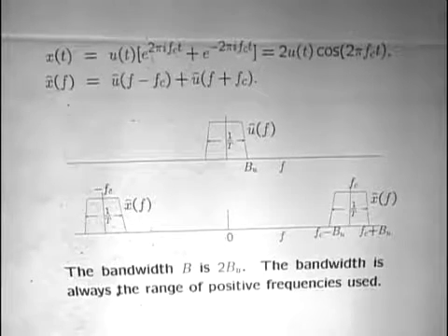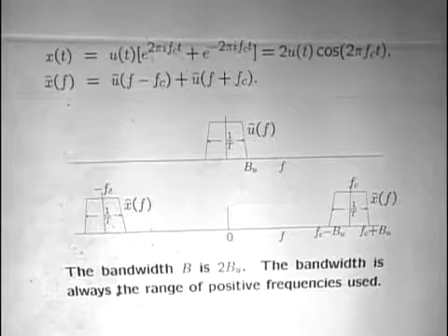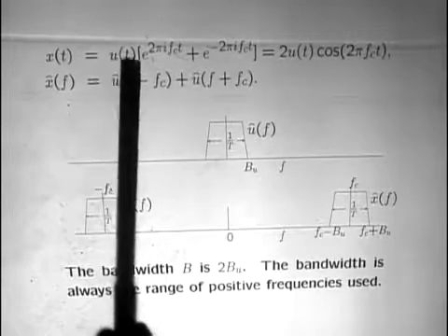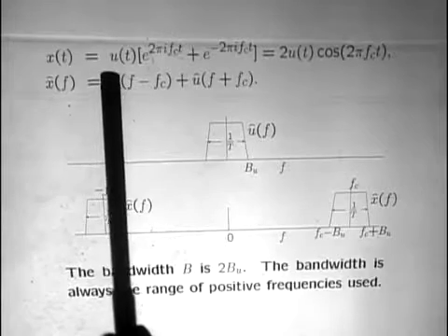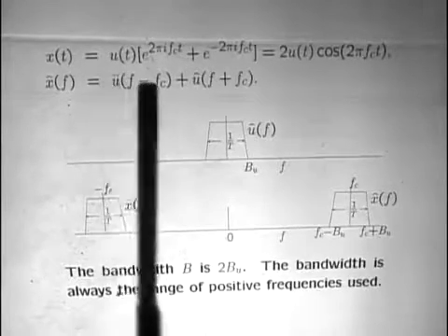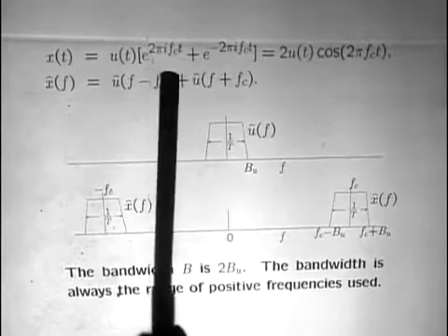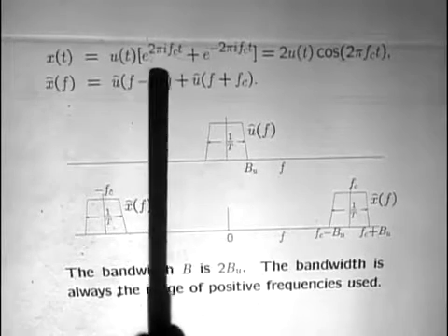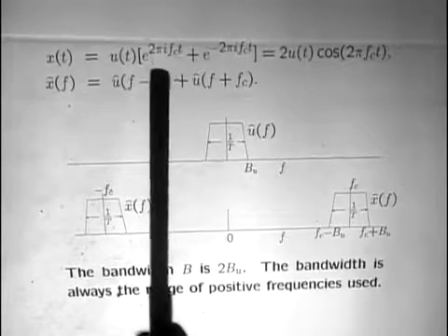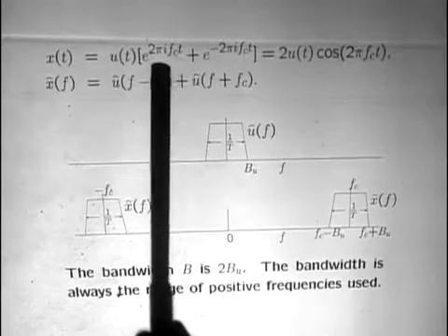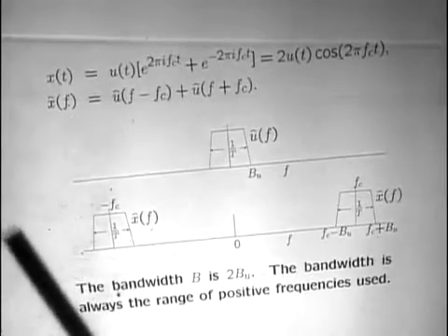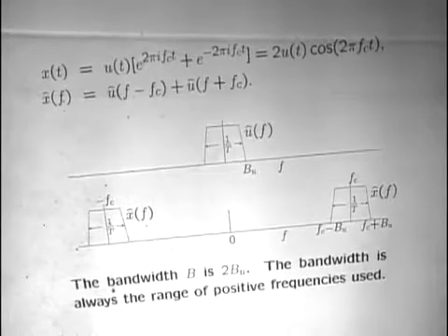And in frequency, what this looks like, since all we're doing here is, by this shift formula that we have for Fourier transforms, multiplying a time waveform by an exponential, by a complex sinusoid, is simply the same as shifting the frequency response.